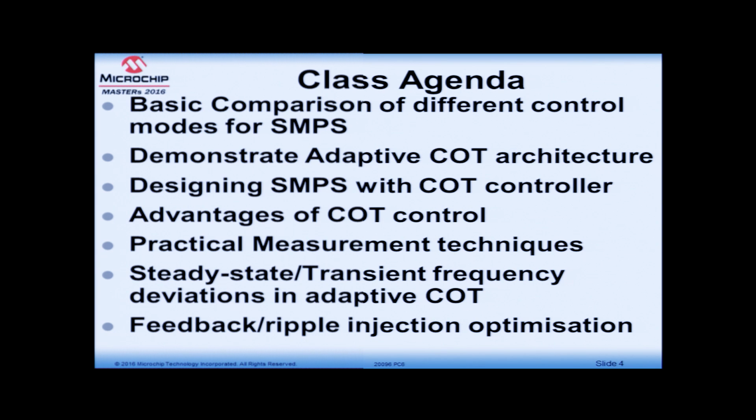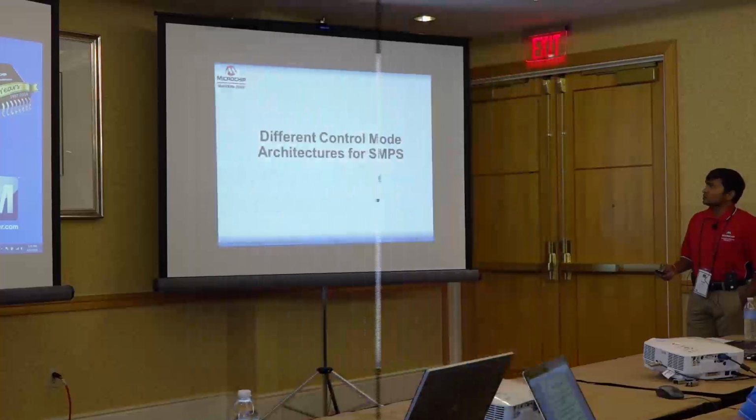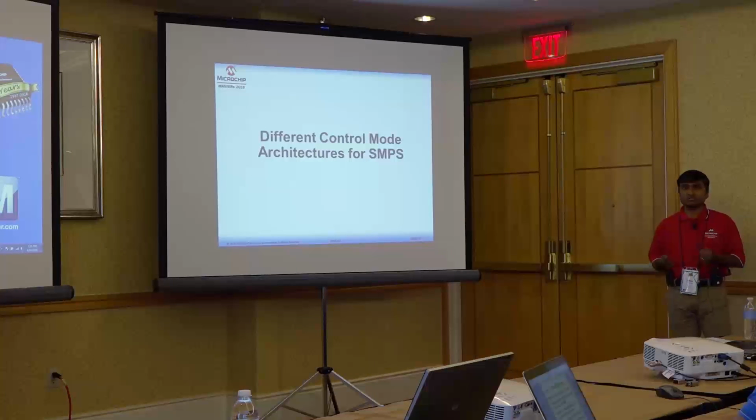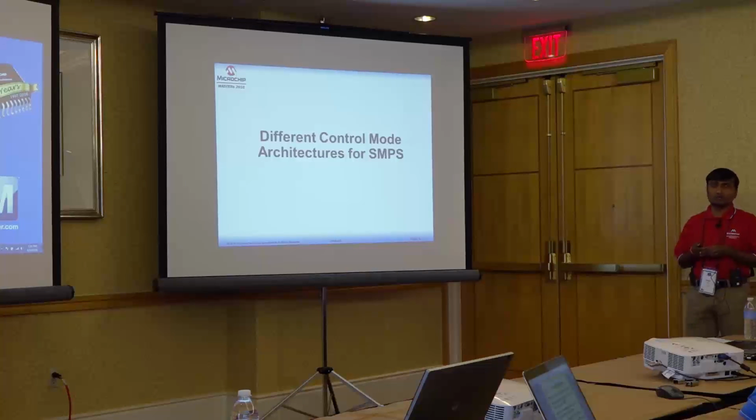We will also go over the practical measurement techniques we generally use on the bench while troubleshooting the power supply, and steady state and transient frequency deviations in adaptive COT. At the end, we will cover feedback and ripple injection optimization for better transient response to further optimize the power supply. So, without delay, I would like to discuss the different control mode architectures available for switched mode power supplies.